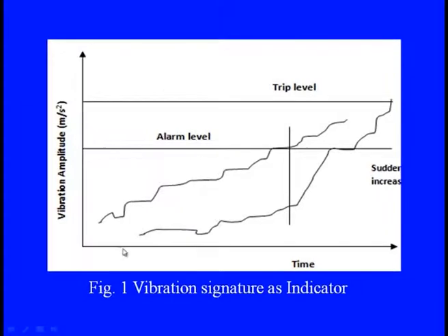When the machine is producing vibration acceleration at this level, this is the comfort level, and no problems are there, because when the machine is in a rotating or translating part or any kind of motion, certainly due to the inertia forces we have varying compliance features and self-excited vibrations. But when things are increasing, that means there are some additional features due to misalignment, unbalance, or various other reasons, such as a defective part in the bearing, gears, or the shaft.